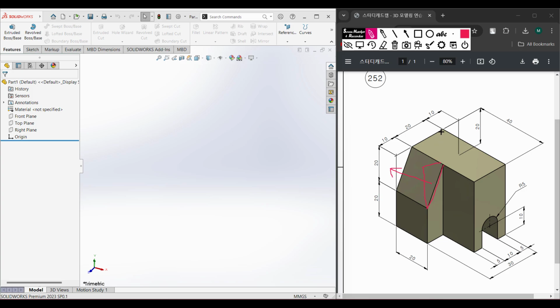After closing this triangle, we'll cut it up to the left side. Okay, then finally we talk about our rectangle cut and semicircle cut. For that we need to first draw a center line here, and this center line has a dimension of 10 unit, and from this center line I'll draw two offset lines, as the total distance is 10 unit, so the half distance will be 5 unit. Okay, then after that we'll use the cap ends arc tool to cap this portion, then we'll close this shape, then we'll cut it up to this side.